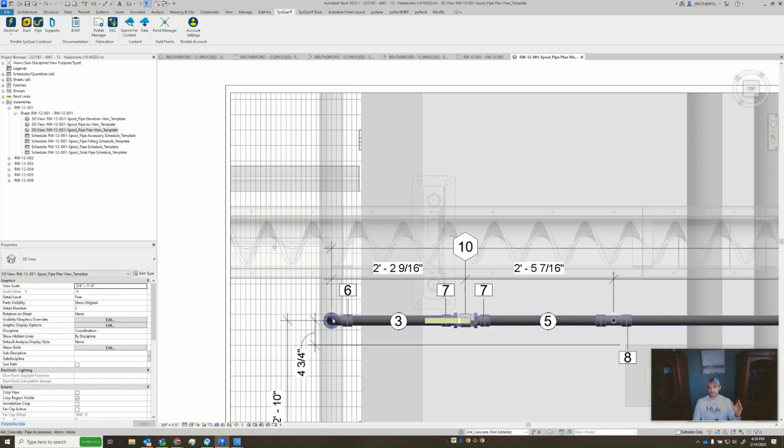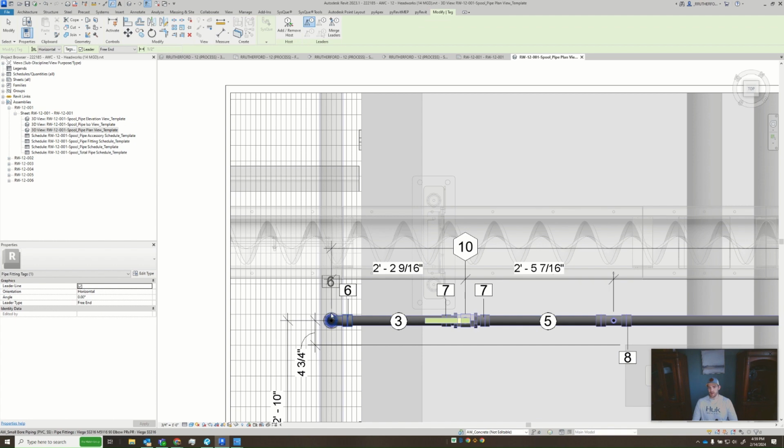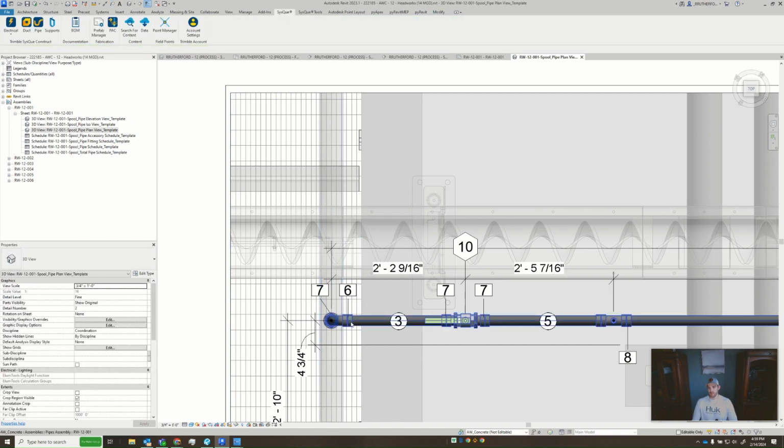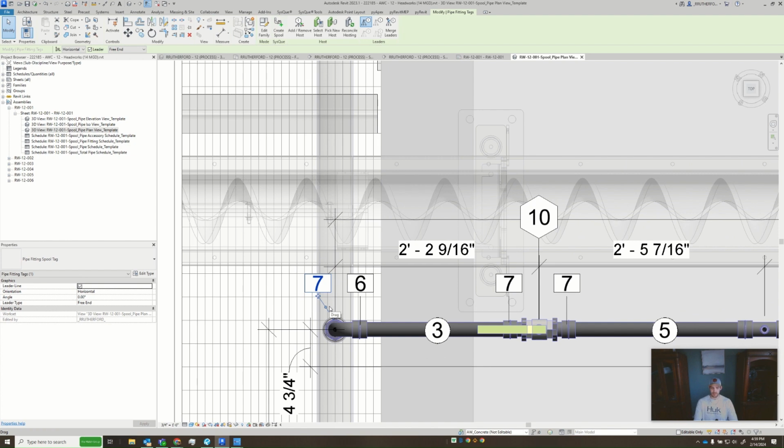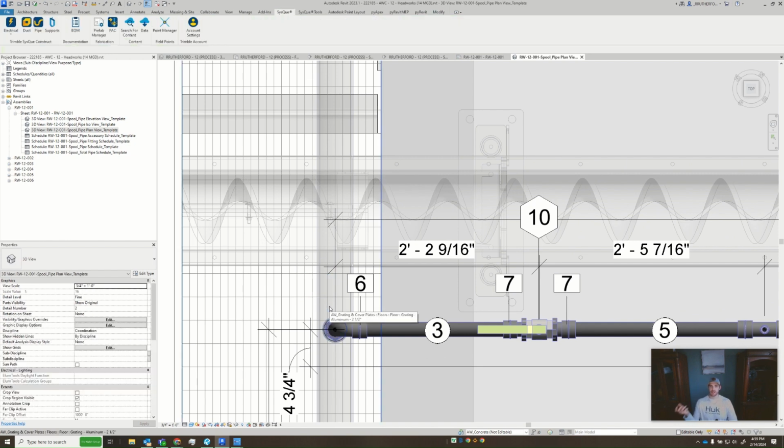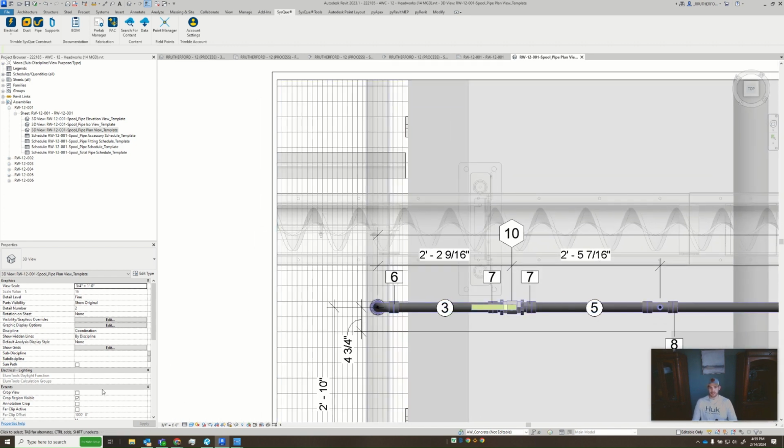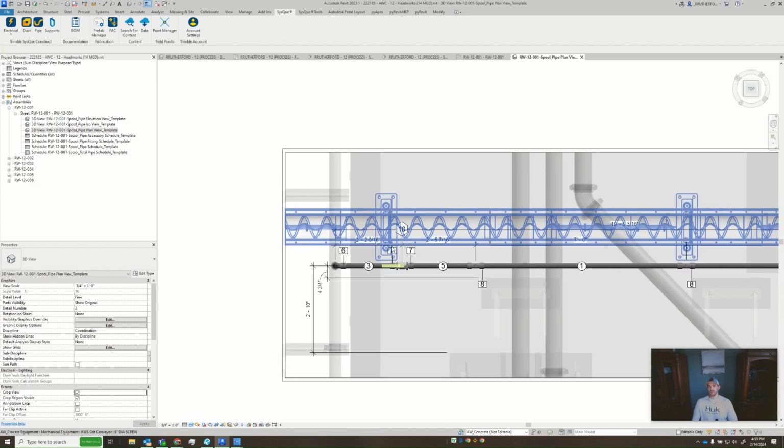I don't want to get stacked elements, because as soon as you start seeing, for instance, if I were to do number 7 here, and they can't see number 7 clearly, they may confuse this particular element with number 7. Now, in this particular case, if they read the bill of materials and saw that that was a male connector, they would pretty quickly understand, hey, that's incorrect. But for some other instances when that's not always the case, it can be difficult to differentiate.